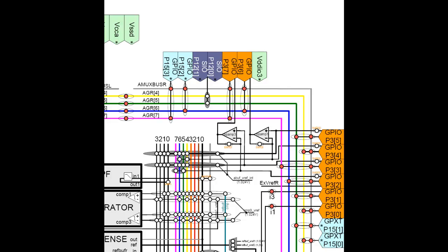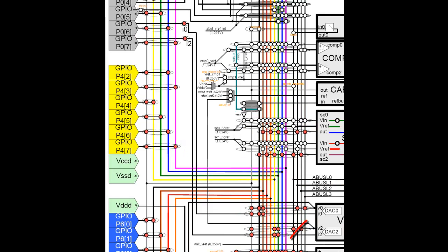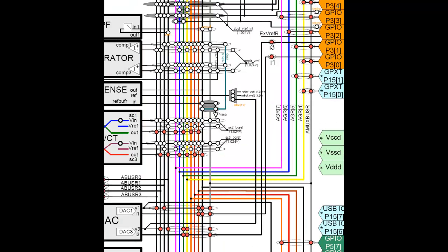When using the IDACs in the high current range, 2 mA, routing through the normal analog matrix may create excessive voltage drop due to switch and trace resistance. Because of this, there is a dedicated pin that may be used for each IDAC. The output for IDAC 0 has a dedicated route to P06, IDAC 2 to P07. On the right-hand side, we have a similar arrangement. Although these dedicated routes are meant for the 2 mA high current range, it is a good idea to use them anytime you can, since they save the precious analog globals for other routes.